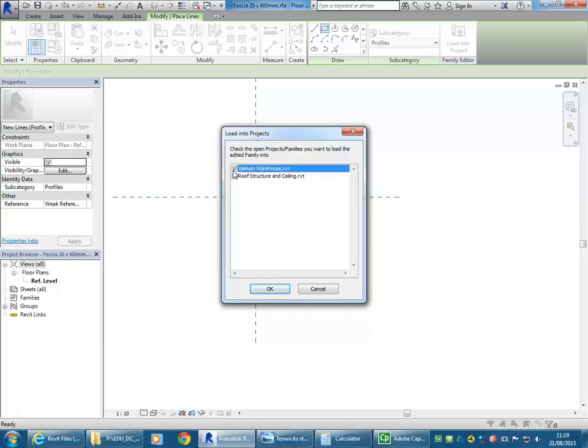Why did you make it actually going down? Oh, because it measures the base point from the top left corner. Oh yeah, it'll automatically know how to go. And then load into family, load into project. We're doing that now. Yeah, that's right.